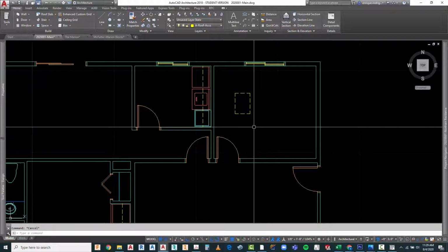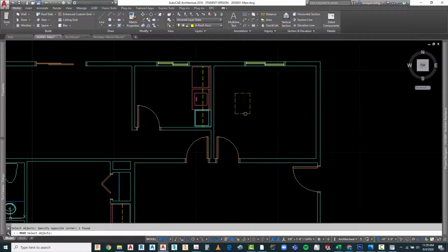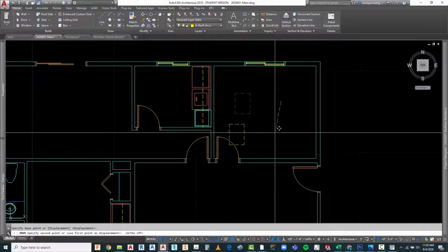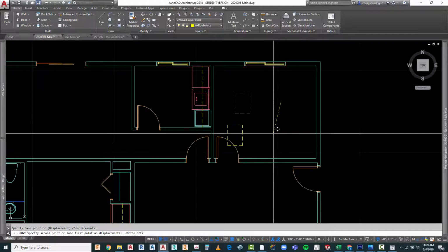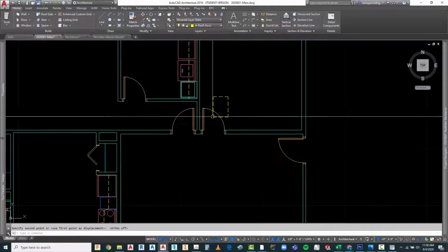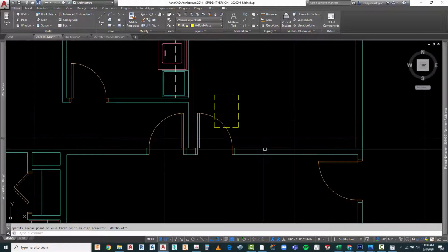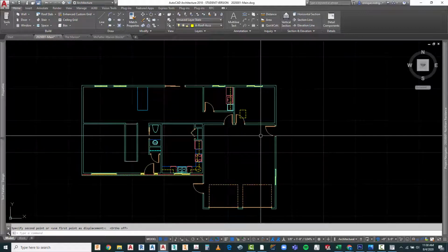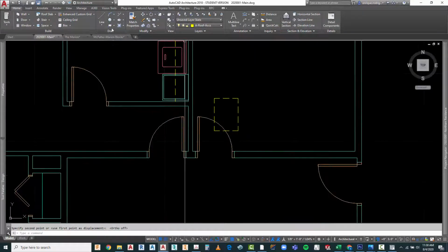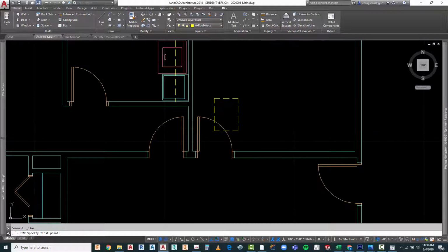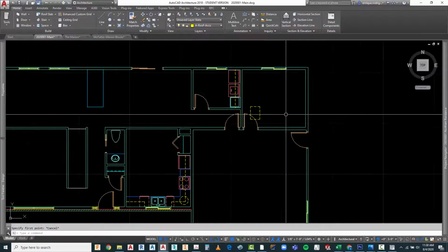There we go. I can move that and locate it right into here. Now that 22 inches is kind of important because it's basically the space in between roof rafters, or in between trusses if you were using trusses. So I'm going to locate it right into there, and that would be something that would be coordinated also out in the field. Now they show a diagonal cross in here. I'm not going to show that. I think that's unnecessary.